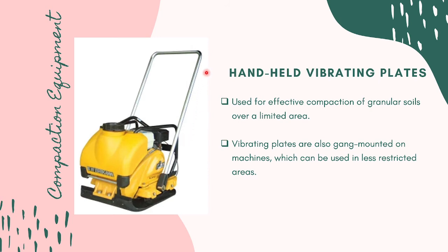Another thing to consider is the space. Think about whether you can bring such large equipment into the project. For example, if your project is in a very remote area and you cannot bring it there, and there is no way for large equipment to pass, you can use the handheld vibrating plates in those cases.